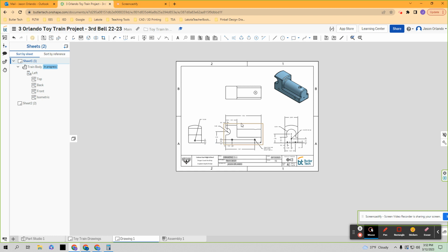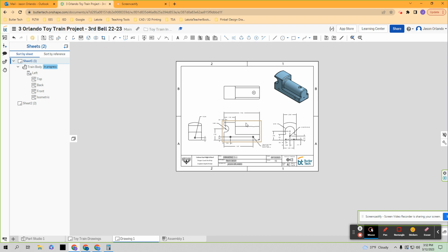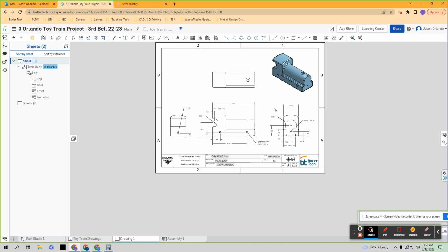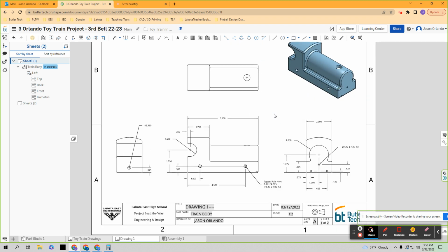So if I've got enough space in here, right, I can sneak this view this way just a little bit if you're thinking this is getting crowded, to be able to have room to bring this. If you think it's getting crowded on the bottom, then just bring this higher a little bit. Because we used the project tool by moving this one vertically, the right and left should move vertically as well. Okay, if you ever move the front one right or left, the top one should scoot right or left as well with it. So you do have to see that moving this one to the right is going to crowd this gap right here. But please take a step back and be mindful of that.